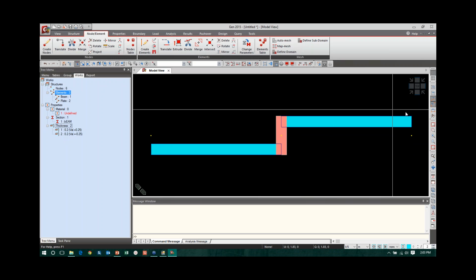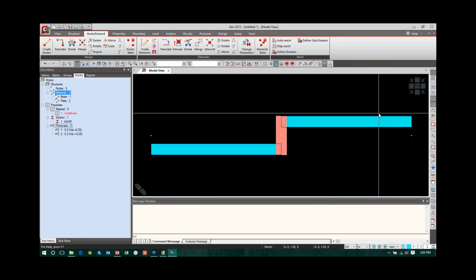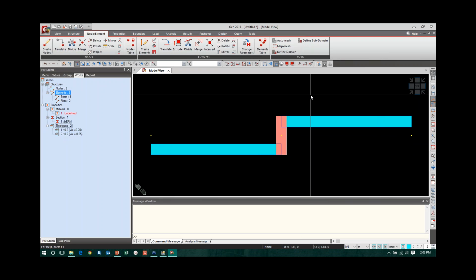So like this also you can model actually. Here the slab is at the same level, but if there is a loading difference on the both ends of the slabs, it creates moments and all. So it's not only the offsets for beams and columns, you can do it for slabs, walls, and everything. You can give the offset commands.